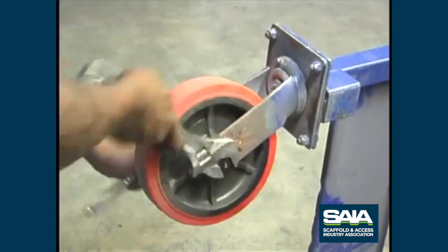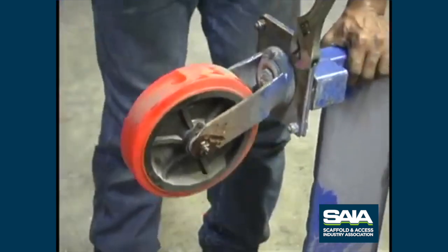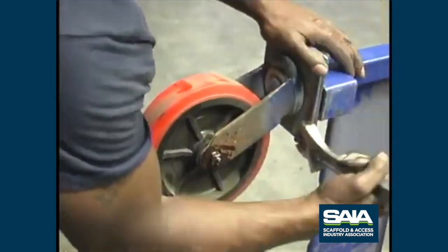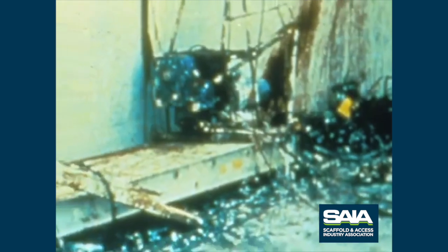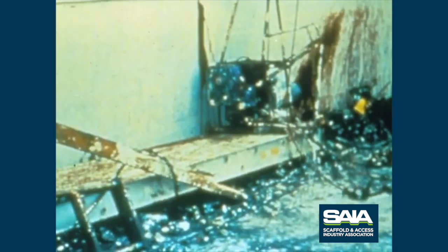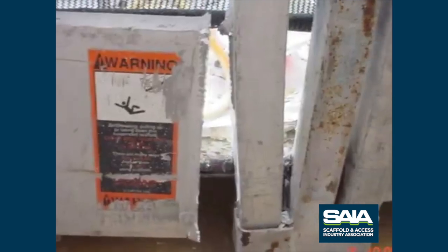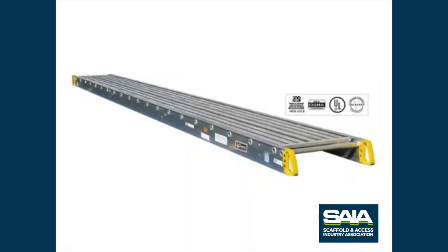Components that fall off while the platform is suspended could kill or seriously injure someone, as well as cause property damage. Is the suspended scaffold damaged by acid? Is there visible damage? Is the platform of the proper rating?